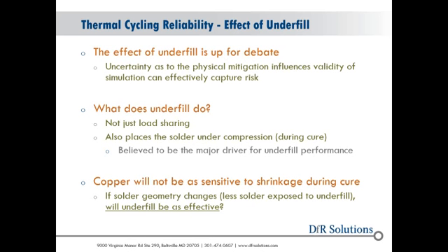It's only compressing a small sliver of solder between the bond pad and the copper pillar. And the copper pillar has a higher modulus, so it's going to be a little more resistant to it. It'll be interesting, but I would not be surprised if underfill is not found to be as effective with this new structure as it is with the flip chip solder bump. In fact, it's almost serendipitous that we're able to use underfill. Underfill really brought about the revolution of flip chip. Before that, you had to put flip chip on ceramic, which was really expensive and kind of a pain. Now I can put flip chip on organic substrate because I've got this underfill. But the underfill benefit may really be derived from the material and the geometries that we were using.